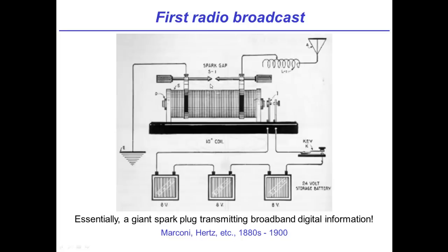Let's say you're listening to music and you plug a speaker into an amplifier, or you unplug the amplifier suddenly and you hear the speaker make a crackling sound. Yeah, definitely. And in fact, that is because when you suddenly rapidly disconnect an electrical signal, it generates a broadband electrical stimulus. And if you connect that to an antenna, then the antenna puts out a broadband electrical stimulus. Oh, so they basically broadcast this electrical signal caused by the spark. Correct. You'd get a spark, and the antenna would essentially then give out a burst of electromagnetic radiation.